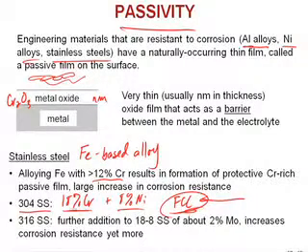Okay, so 304 stainless steel, 18% chromium, 8 nickel. We get a protective chromium oxide layer on the surface. If we need more corrosion resistance, if we have a more aggressive environment than our kitchen, let's say, we can add more alloying elements. If we add 2% molybdenum, the next step up is 316 stainless steel. Very corrosion-resistant material. Okay? But we can add more things.